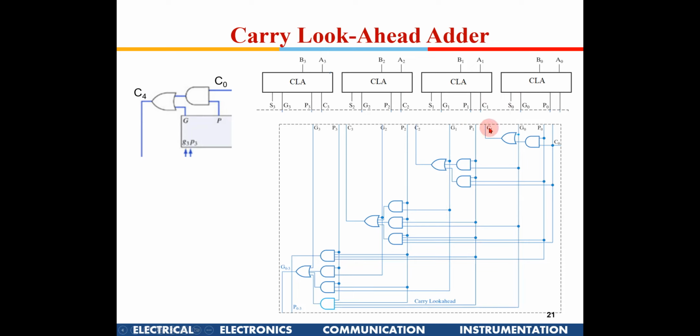So for carry 1 2 gate delays, carry 2 2 gate delays, carry 3 also is 3 gate delays. So there are no additional delays as you are moving from one carry to the other. Okay, now for this particular block I am not going to generate carry 4 in a similar manner. What I am going to do is generate for this entire block and propagate for this entire block. So this propagate is only the AND of all the 4 propagates, and generate is like propagate from the previous and generate from the other previous.